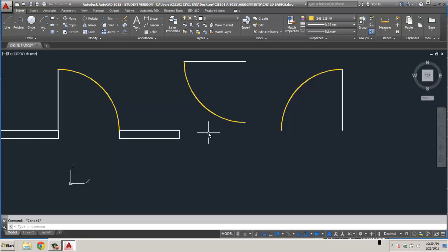A lot of times you draw something once, you don't want to have to keep drawing it over and over again. You can make a library of these objects. These are just basic two-dimensional drawing tools, so it's not really that big a deal. Now, they talk in this chapter, if we move on to the ellipse, which starts on page 151, it's 3.11, the ellipse. An ellipse has a minor axis and a major axis, and we do use this quite a bit.